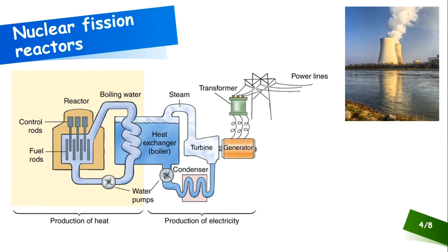You basically want to absorb those neutrons that get split off when you get the fission of the atom into two atoms. If you don't absorb those neutrons, then they just keep growing and multiplying, and the reaction gets really out of hand. So you've got to be able to control that. The way we control that is with control rods. We slip the control rods in between the fuel rods, and they absorb those excess neutrons and everything calms down. When we remove the control rods, the reaction keeps going and going.